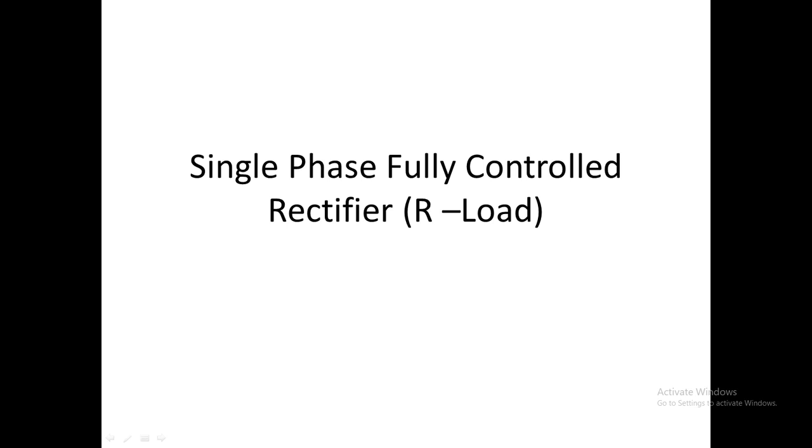So today we are going to see single phase fully controlled rectifier, or single phase fully controlled converters. Fully controlled in the sense that all the devices are fully controlled devices, that is, we are using SCRs. It is a single phase full wave rectifier constructed using SCRs, and it is fully controlled in the sense we can vary the output voltage.